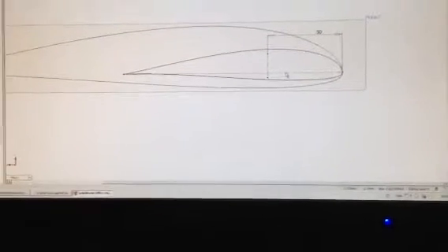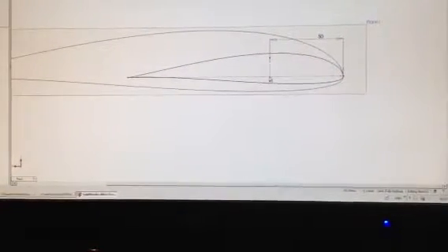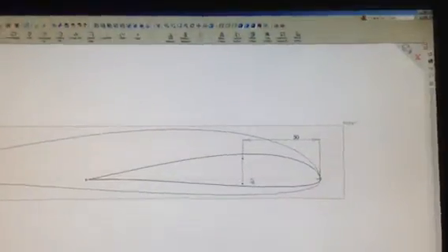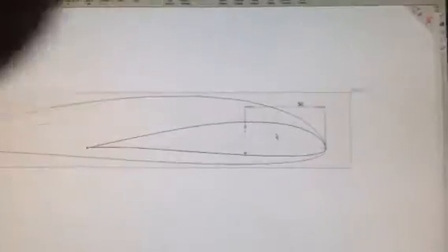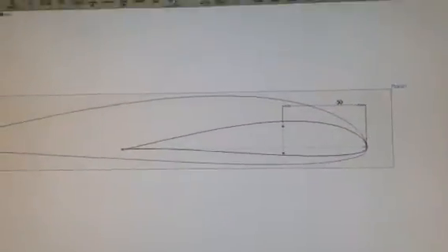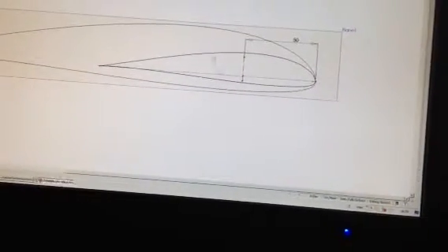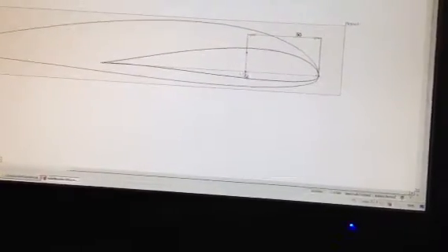So I want to draw a point at the intersection of these two lines. So I select the first line. I can hold Control. I've only got one hand, so I'm going to have to put the phone down for a second. So I'm going to press Control and hold Control in and click on the other line. Okay, so both lines are now selected. And I'm going to click the Draw Point button. So that puts a little asterisk on the intersection point.